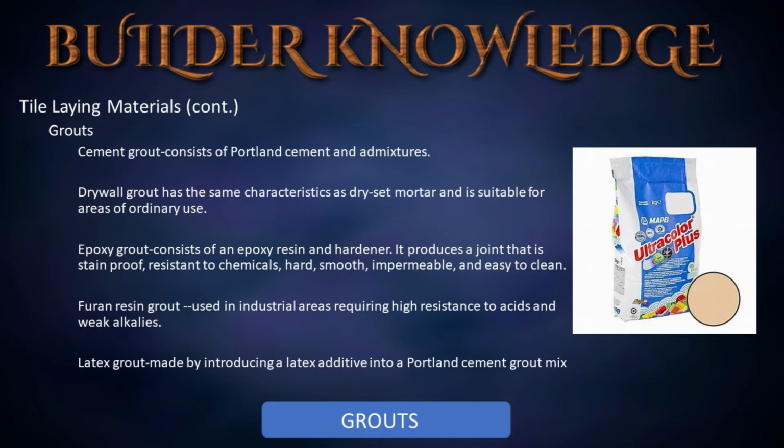Okay, on to epoxy grout. It consists of an epoxy resin and hardener. It produces a joint that is stain-proof, resistant to chemicals, hard, smooth, impermeable, and easy to clean. Epoxy grout is used extensively in counters that must be kept sanitary, for foods and chemicals.